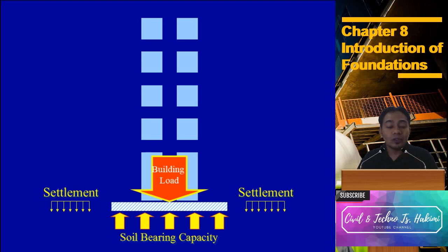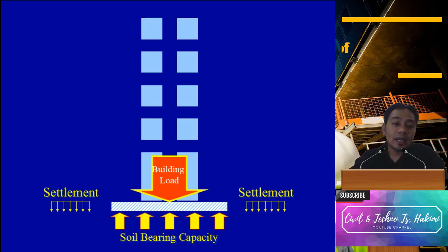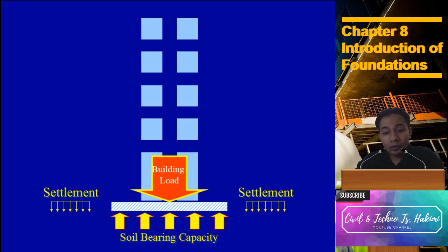So that's why, before the construction process, we need to investigate the soil stratum layer to decide whether we want to use a shallow foundation or a deep foundation. These are the two categories of foundations.